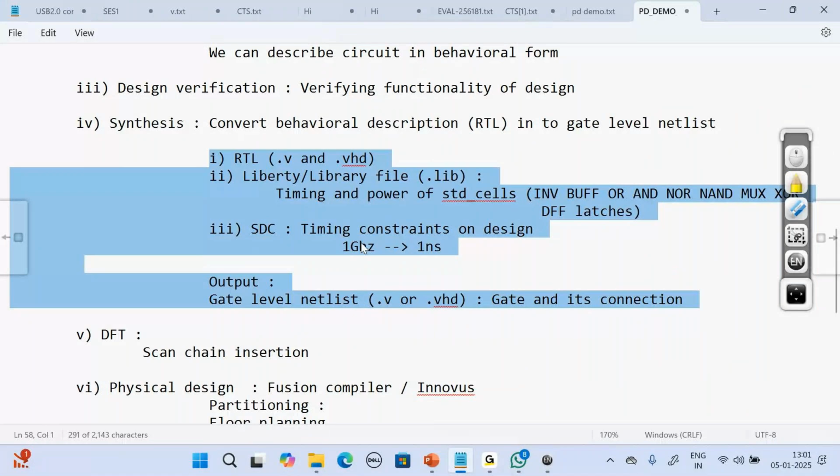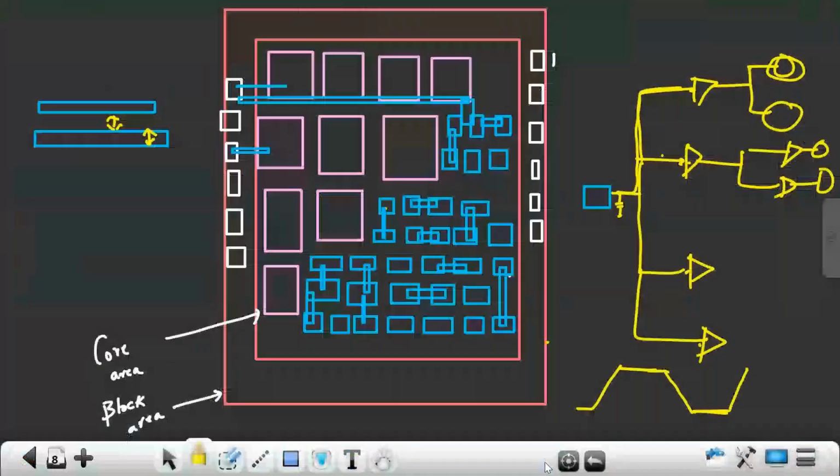So logical synthesis is very easy, but physical aware synthesis is more involved, and you will learn the advantage of physical aware synthesis. Physical aware synthesis has a lot of advantages because during synthesis itself my tool will place the cells. It will estimate the net length. It will calculate cell delay and net delay. If timing is not met, my tool will do reordering and logical restructuring. I mean, it will change the cells.